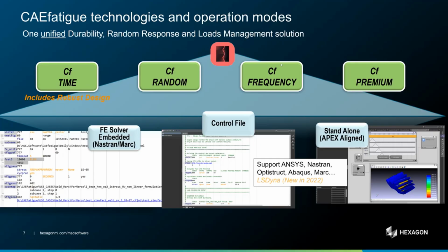Then we can do vibration fatigue. In the vibration fatigue domain, we normally refer to stochastic processes, but also sometimes you have sine sweep analysis, and maybe you want to combine deterministic sine sweep with random processes, or maybe you add random on random.